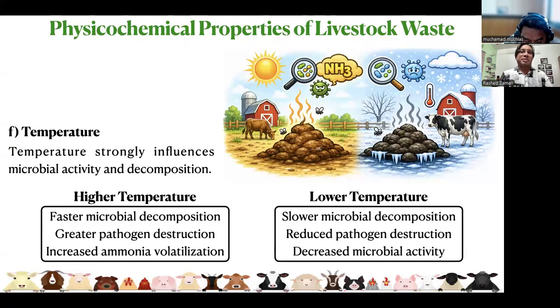And in the physical properties, next we have the temperature. Temperature is another important factor, and it strongly influences the activity of the microorganisms during decomposition. Because in case of higher temperature, generally the decomposition rate of the microorganisms gets faster, because as the temperature gets higher, it helps the microorganisms to grow fast. Ultimately, it increases the decomposition rate.